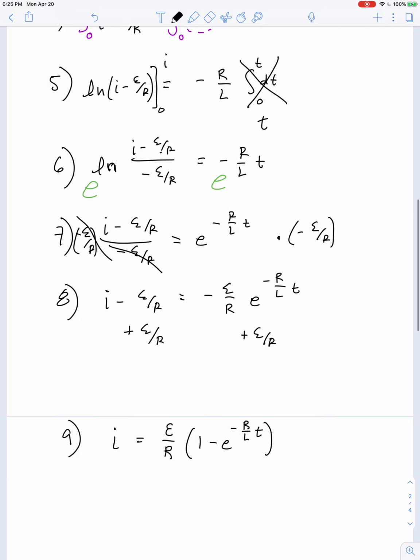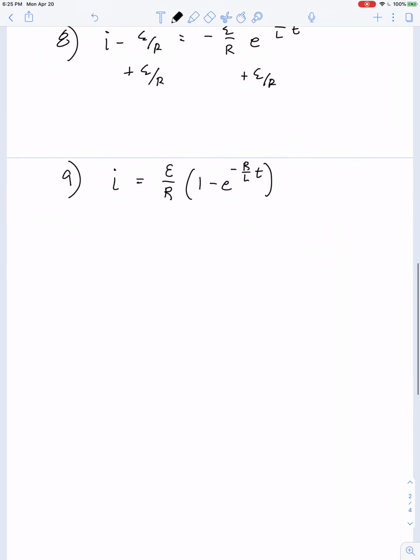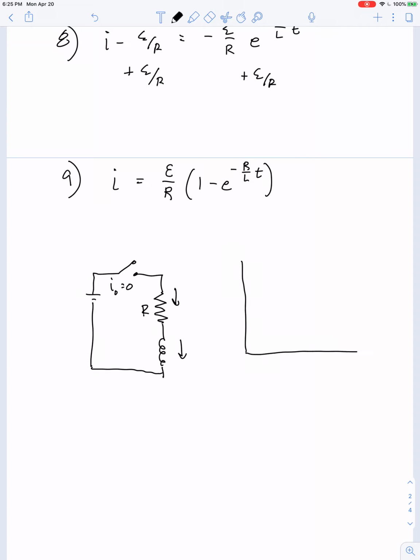So it's a similar expression here. What's gradually increasing in time from the moment the switch is thrown is not an amount of charge, it's an amount of current that's gradually growing. The current that passes through the resistor, and therefore passes through the inductor since they're in series, goes from an initial value of 0 up to some maximum value, and a graph looks something like this.